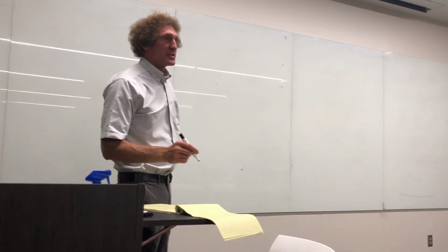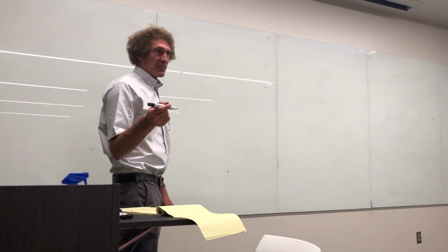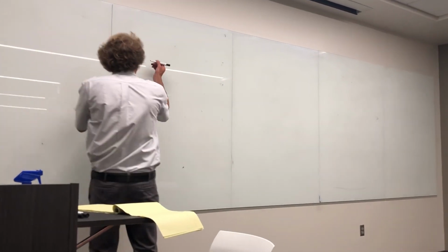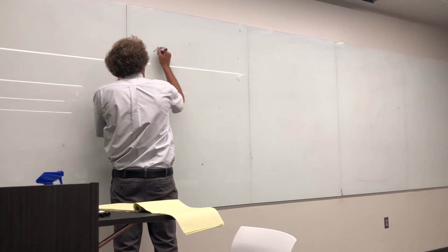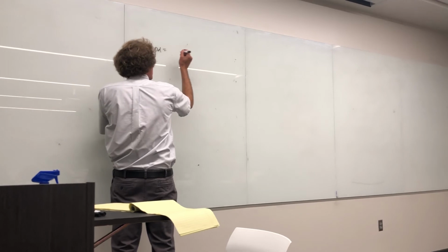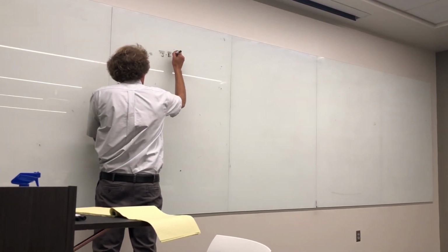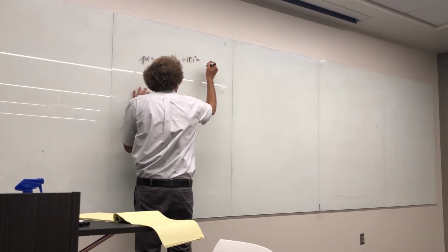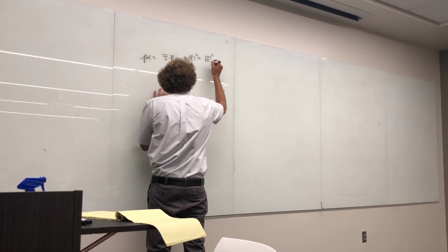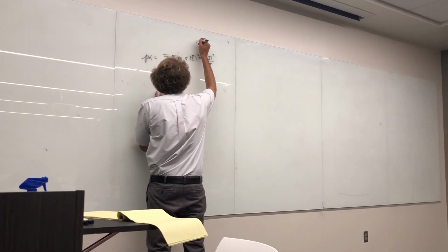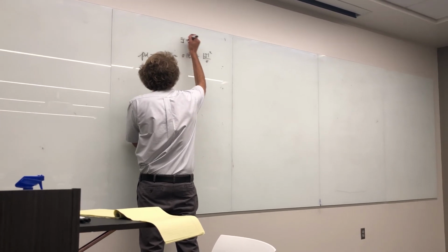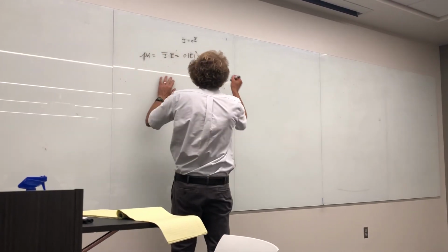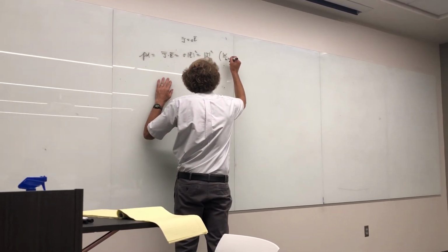I want to talk about energy density. I gave you that the energy in a capacitor is 1/2 CV squared, right? But there's something called the energy density. It's like power density. Do you remember what the power density was in a material? It was J dot E, or it was equal to sigma times the magnitude of E squared, or it was equal to J squared over sigma. And remember that sigma times E is equal to J, where sigma is the conductivity. Now this is a power density, and that's in watts per meter cubed.